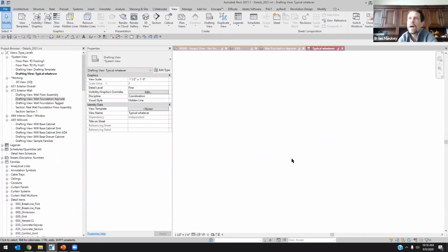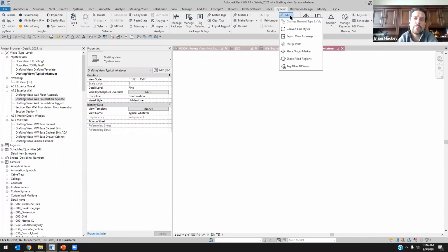And if I export this out to something else like a CAD file or to anybody else, I want to know where the 0,0 is so it makes logical sense, right? There are tools out there. One of my favorite tools in PyRevit is the simple capability to say place origin marker. And PyRevit will literally put an X at the 0,0 of this view. One of my favorite tools. So now when I'm modeling in any view in Revit, I know where the 0,0 is.